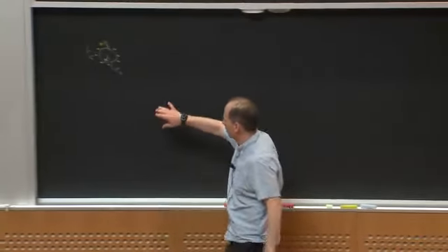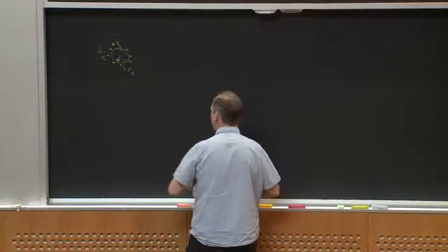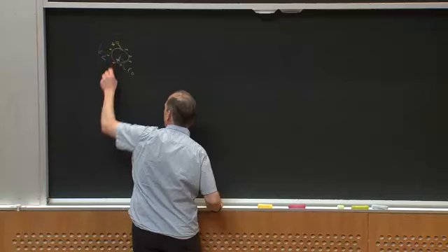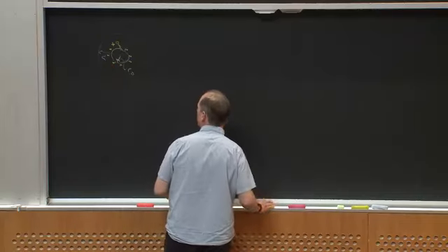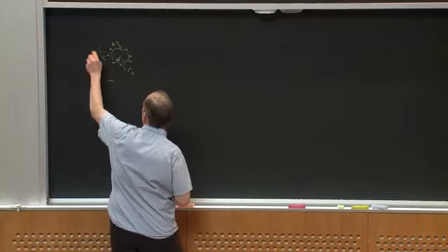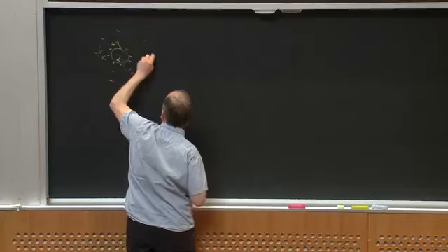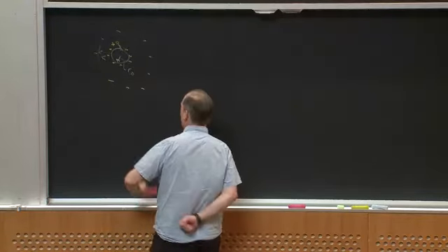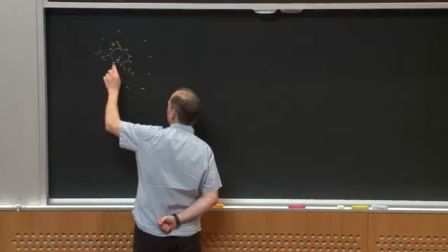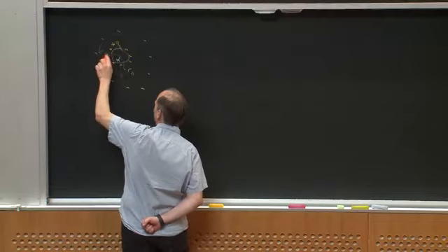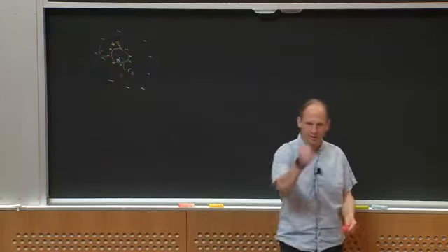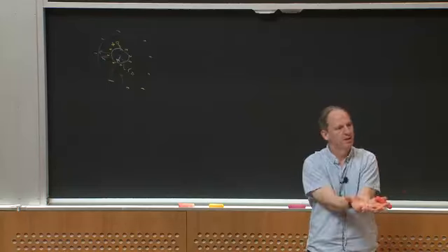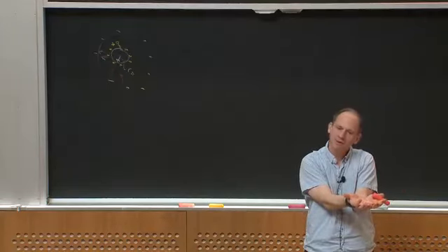That itself forms a capacitance, where I'm going to have mirror charges distributed on my outer sphere, and I'm going to have electric field pointing outward like this. Does that make sense to everybody? The picture I'm drawing, I've got an inner sphere and an outer sphere, and I want to calculate the capacitance between them.